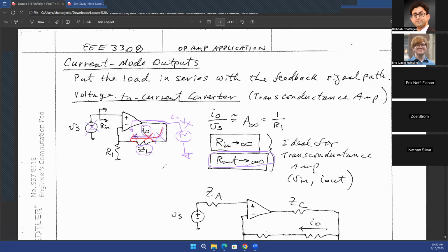And if there is 0 current at your output and you have connected a voltage source Vx over here, the ratio of Vx over 0 current is going to be the output resistance at the point where you're considering your output, right? So Vx divided by 0, that's why your Rout in this case is infinitely large. Even though the op-amp's output resistance is still 0. The op-amp is an ideal op-amp. The output resistance looking into the op-amp at the output port is still 0.